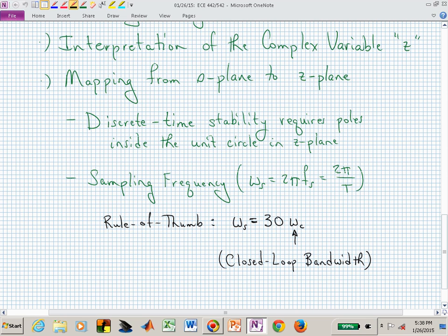If somebody now says, I want you to build me a low-pass filter, you say, okay, I can do that digitally. Well, maybe you're more comfortable with designing an analog low-pass filter, but we will learn ways to map those continuous time filters or those S-domain transfer functions into Z-domain transfer functions.